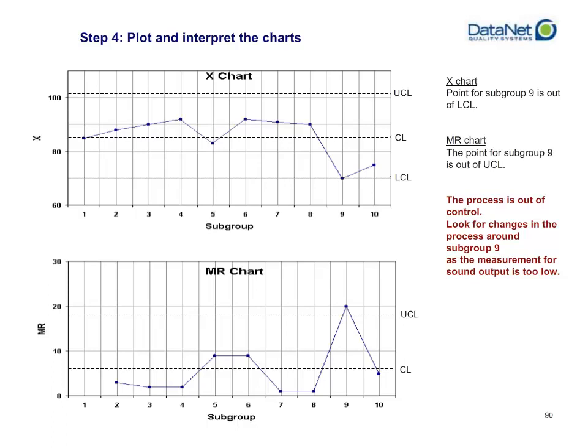When you go ahead and plot your control limits and actually plot your X values and your MR values, you're going to see that your process, when you start to analyze this, between subgroups 1 to 8 looks pretty good. Something happened at subgroup number 9 where you were out of control for sure in your MR, your moving range. The volatility of your process absolutely skyrocketed. And it shows up also in your X chart where you're starting to get low values and extremely low values. You would definitely want to investigate what happened over there to figure out why that was happening.